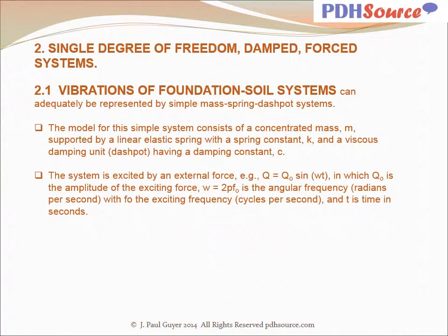Vibrations of foundation soil systems can adequately be represented by simple mass spring dashpot systems. The model for this simple system consists of a concentrated mass M supported by a linear elastic spring with a spring constant of K and a viscous damping unit or dashpot having a damping constant C.